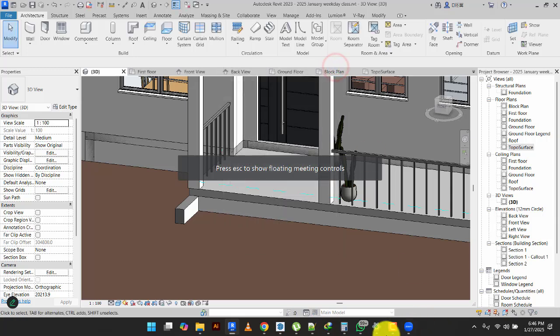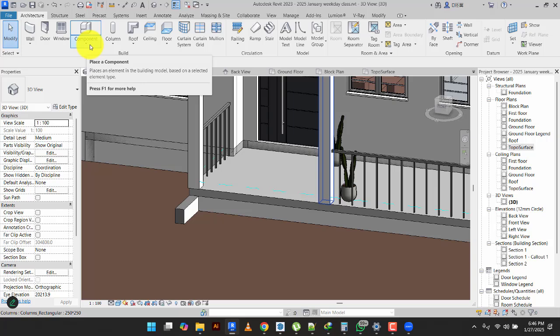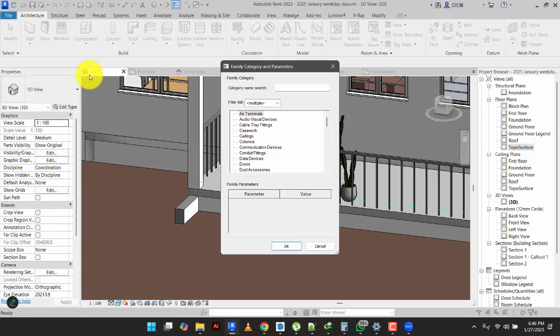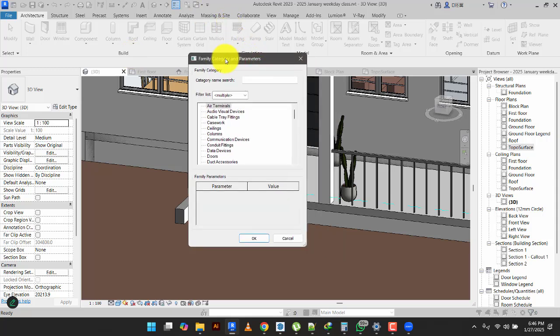Okay, so let me start this process. You click on the component, the arrow and the component. Then click on model in place. Then you get this pop-up asking you that the thing you want to create, which category does it belong to? So this we can associate it with the floor, but it's not compulsory. Don't worry yourself looking for category. Just choose what we call generic model. It means general model. Just pick it and draw and you're gone.